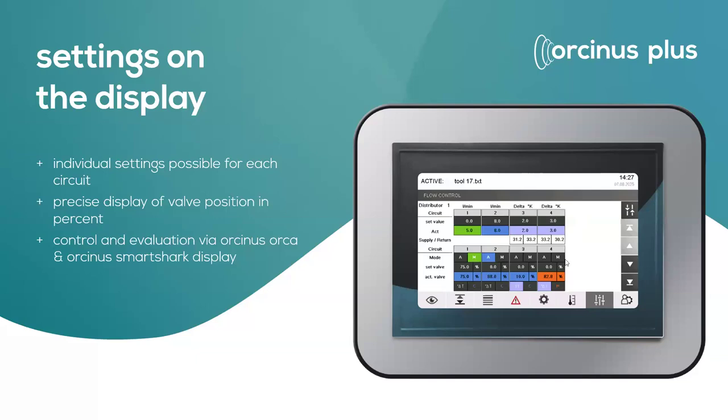Here you can do the settings for the plus version. So you can say, I need a delta T or the flow. And here you see the percentage of the valve, so it gives you information. Is it open? Is it half open? Or in this case, it's 75% open. So you have an idea of what's happening inside.